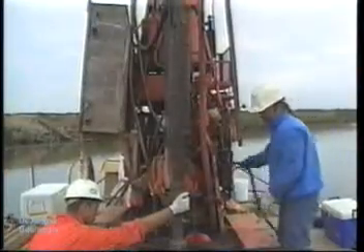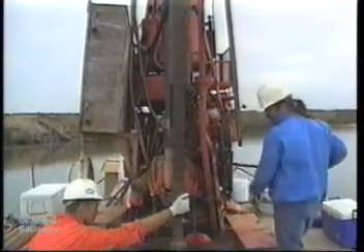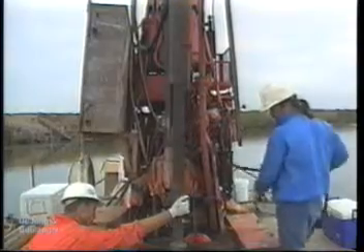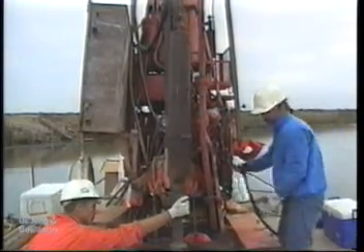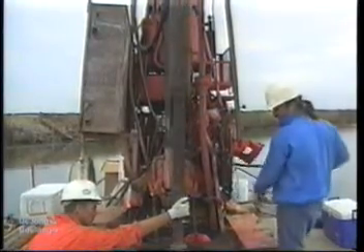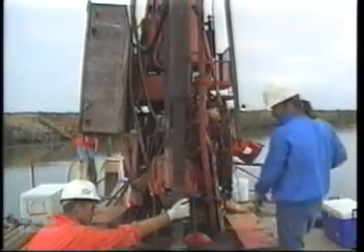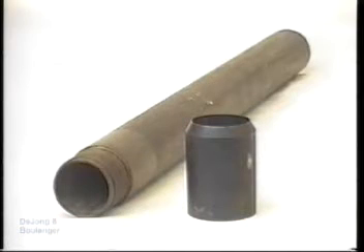When mud rotary drilling in cohesionless or highly erodible soils, an outer casing is used to create a closed circulation system. Casing is advanced concurrently with drilling until it is seated in dense, unerodable soil or rock. A shoe, made of hardened steel, is attached to the bottom of the lead casing to prevent the casing from buckling while it is driven into the soil by the hammer.